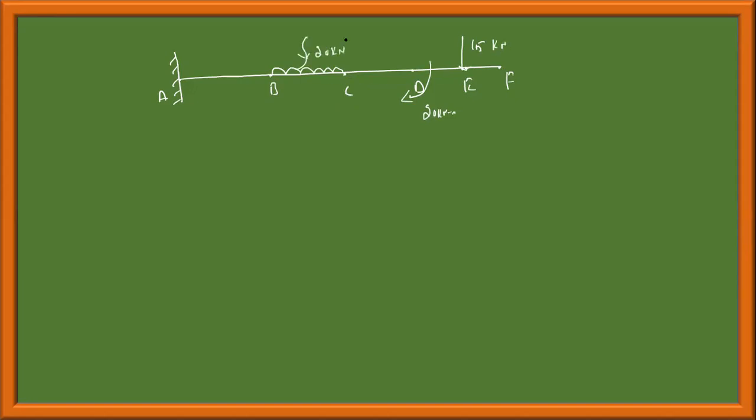Okay. I'll draw one more sketch for the shear force and bending moment diagram, one below the other. Draw a line for the shear force diagram, a horizontal line, and for the bending moment diagram, one more horizontal line.